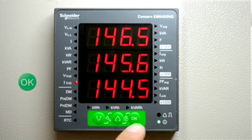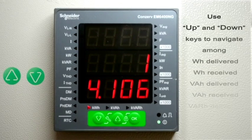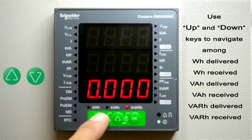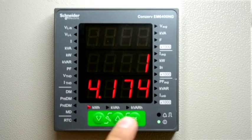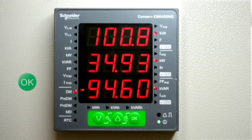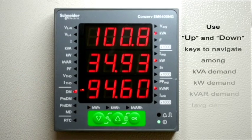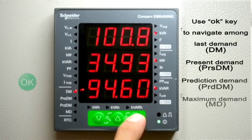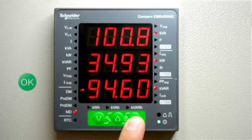If we press OK, the meter navigates to energy block and you can navigate through different energy parameters by pressing up and down arrow keys. Pressing the OK key again navigates the meter to demand section. There are 4 pages inside the demand section to display demand related measurements such as last interval demand, present demand, prediction demand and maximum demand.